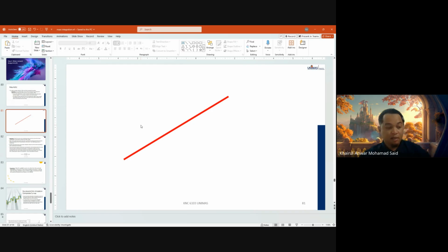So meaning the water source with the concentration higher than the pinch to a sink with the concentration lower than the pinch. This is the cardinal sin of water network design, meaning water here cannot pass through this pinch and vice versa.